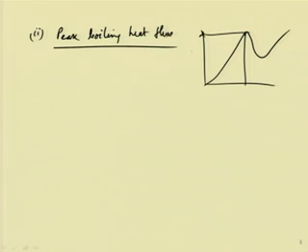So, this critical heat flux also is called maximum heat flux, also it is called peak boiling heat flux, because that boiling is happening at the peak condition. So, if I just draw again here, we had the boiling flux like this. So, this is the region, and here this is called the critical heat flux condition. So, Q dot max is the critical heat flux condition, and this is the excess temperature for that. Okay. Now, this is the boiling curve.